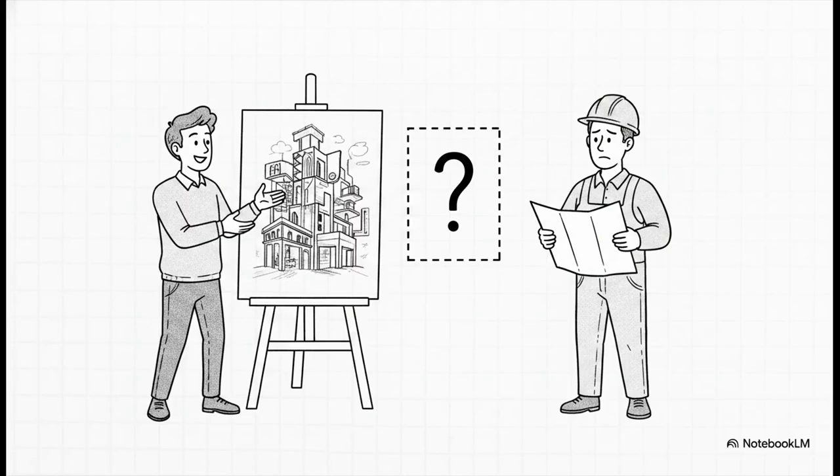You absolutely must separate these two concepts to accurately evaluate claims and avoid the serious risk of double recovery. And then we have constructive change. This happens when the scope of work clearly shifts, but there's no written variation order to back it up. So here's a quick reality test. What happens when an architect issues revised drawings that obviously require more work, but no official variation order ever follows? Well, failure to issue that written variation is actually a breach by the employer. The contractor still absolutely needs to be compensated for that change, and failing to recognize this constructive change is a huge source of nasty disputes at the final account stage.